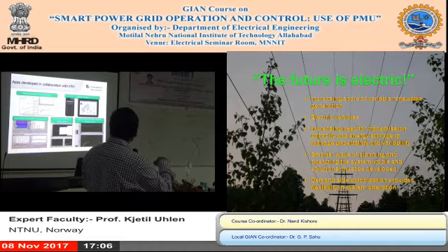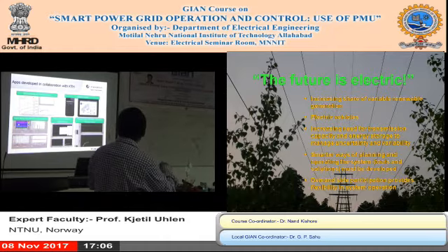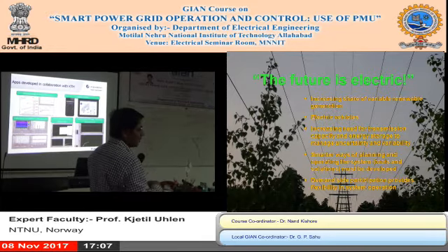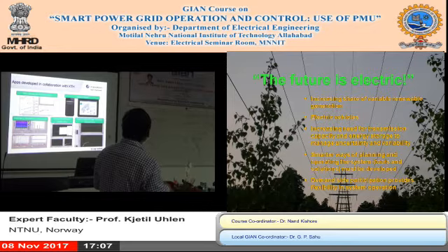From here we can know what is the most sensitive frequency of oscillation. And on this part, because we have several PMUs installed in the Norway grid, it is possible that with the use of the PMU signals from this point, the phase of oscillations can be monitored. So that is how they have worked on the development of the visualization toolbox out of the project.